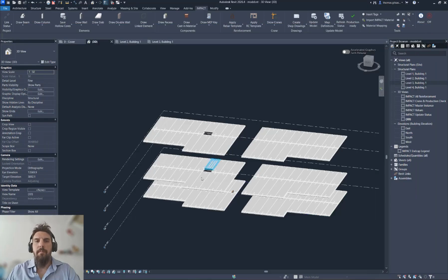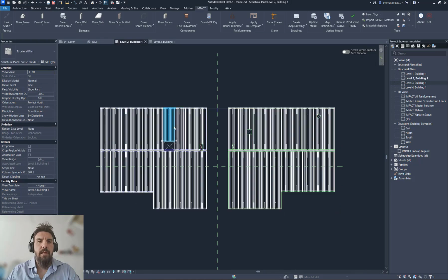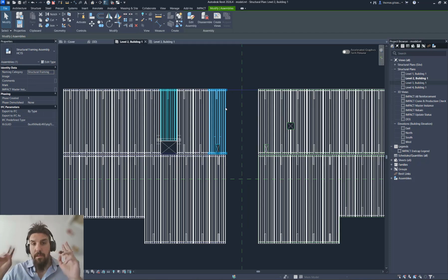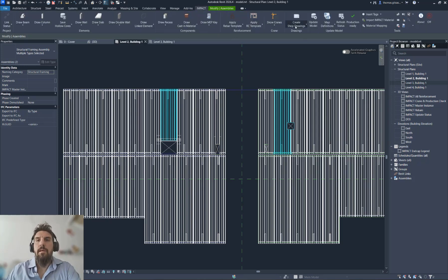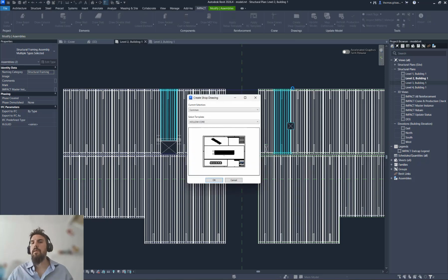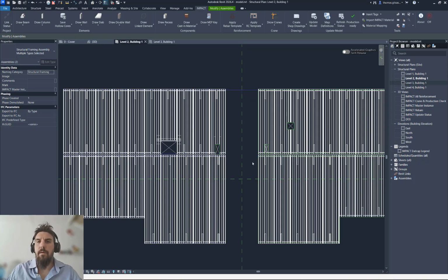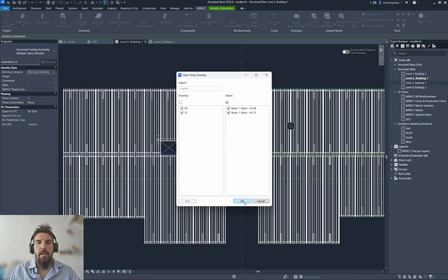So now, instead of going and showing all of them, as you see, saving took a couple of minutes. I will just generate the subdrawing for one of them. At least the one that I can see here is the most complicated one, or let's say I'll take those two, right? I will go to Impact and create a subdrawing. In Impact it is irrelevant to create a subdrawing per element. Sometimes, when you have multiple elements with the same element mark, you only create one subdrawing per element mark, right? So you can have it and then we can go open it.